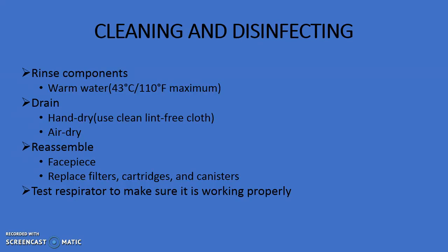Next, you should rinse components thoroughly in clean, warm, running water with a temperature of 43 degrees Celsius or 110 degrees Fahrenheit. The importance of thorough rinsing cannot be overemphasized. Detergents or disinfectants that dry on face pieces may result in dermatitis. In addition, some disinfectants may cause deterioration of rubber or corrosion of metal parts if not completely removed.